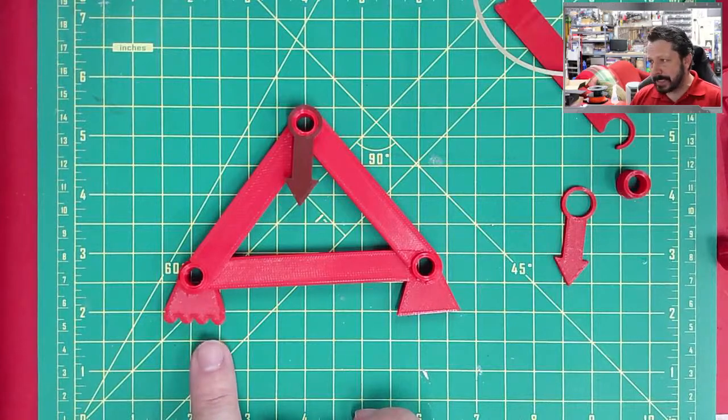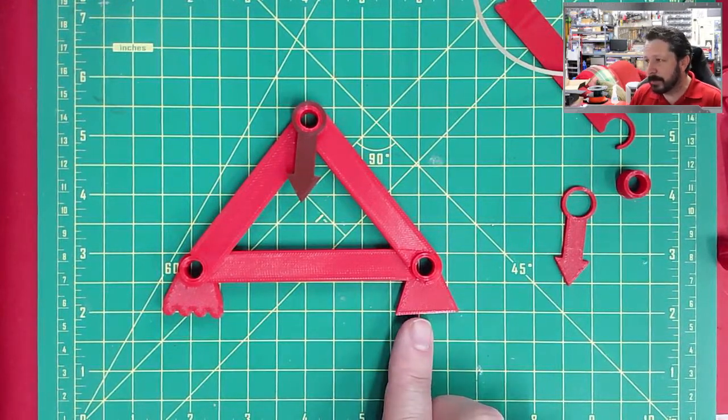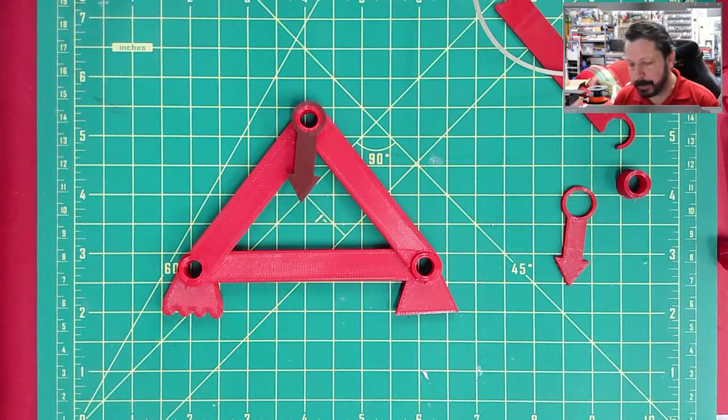So it might seem weird that we put wheels on one end of our truss and not on the other end. But there are practical reasons why you want to at least model it that way. Whether or not you literally put wheels on the bridge is different. You probably don't. You probably put some allowance for expansion and contraction. And we model it as a roller.